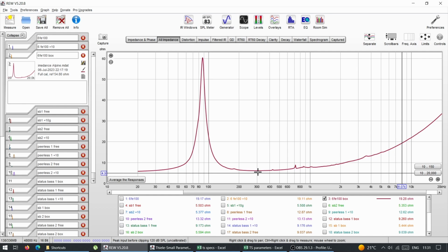However, they appear at higher frequencies, like above 200 hertz. So if you do an impedance sweep on a subwoofer and you see some blips at 200-300 hertz, they don't matter, just because the subwoofer doesn't play that high. A subwoofer plays only below 80 hertz in this region, so anything that happens here doesn't really matter. However, for full-range boxes like bookshelf speakers, where we have a mid bass playing all the way up to 3K or something, these matter a lot.